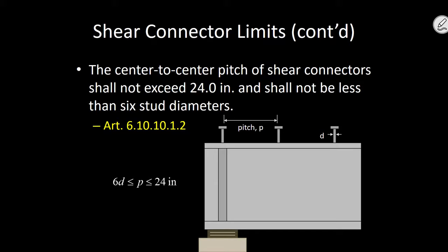You know, theoretically, if you were looking at, let's say, a simply supported beam with a uniformly distributed load, the maximum shear is at the supports, and in the middle of the beam there's no shear, right? These are shear studs. So theoretically, in the middle of the beam, you would need no studs because there's no shear, okay? But the spec says even in regions of somewhat low shear, if you're going to use a composite bridge, you need to ensure that it is composite. So you have to provide some modicum of shear studs.